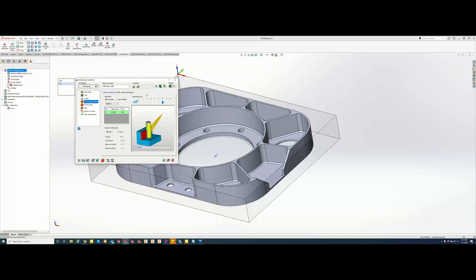into the cut. So if we are running level 8 here, we're going to want a good tool holder, good clamping power on the part, because we're not going to want to run this part on a vacuum fixture running level 8. We're going to get too much pressure from that tool. So good vise, good tool holder, good tooling and stuff like that. Now, if you are running more on that vacuum table side of things, then dial it back down to that 2 or 3 mark.